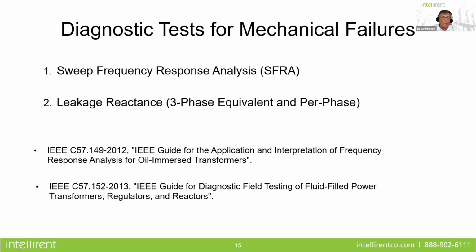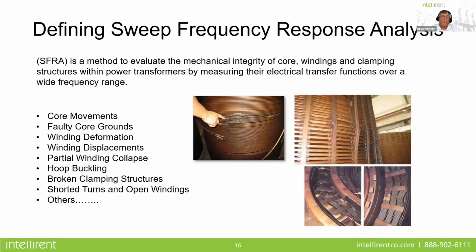And then the other is C57152, which is the guide for diagnostic field testing of oil-filled power transformers, regulators, and reactors. And that covers the leakage reactance test, as well as many others too. Very valuable guide. So SFRA, sweep frequency response analysis.